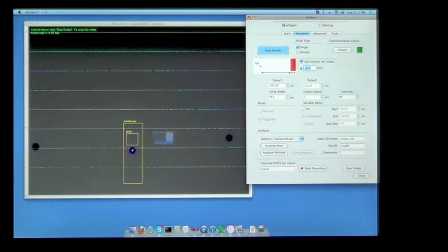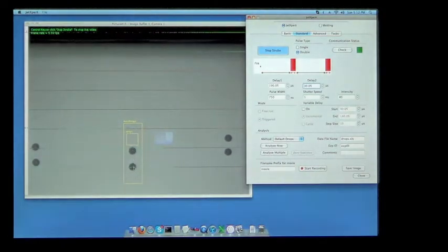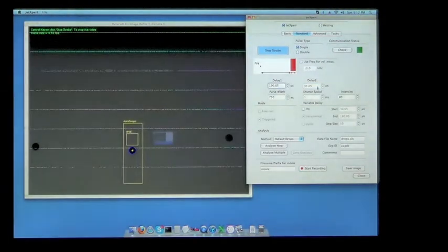Remember, what's needed to calculate velocity and trajectory is to know the distance that the drop travels over a certain period of time. This works with double strobe because we know the time delay between the images of the drops, and we've calibrated so we know the distance in real-world units. It works just as well this way because if you've entered the jetting frequency, we know the time between the drops, and as before, since we've calibrated, we know the distance. Most people do not need this setting, but it's important to know if you do need it.